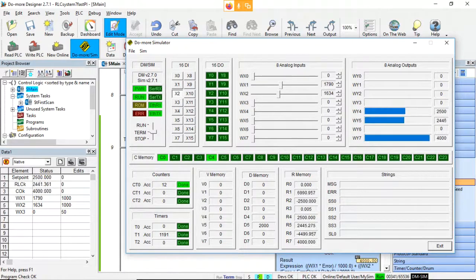Okay, now right there it's out of control. Okay, so you see that just bouncing around like that. It's just the gains are way, way too high. Okay, I may also have a calculation error somewhere. I may have to go back and double check my calculation.